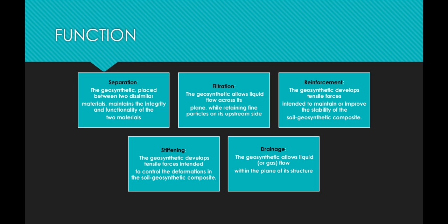First, separating. The geosynthetic placed between two dissimilar materials maintains the integrity and functionality of the two materials. Second, filtration. The geosynthetic allows liquid flow across its plane while retaining fine particles on its upstream side.